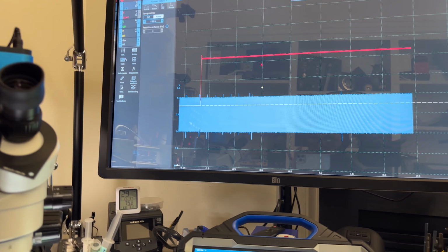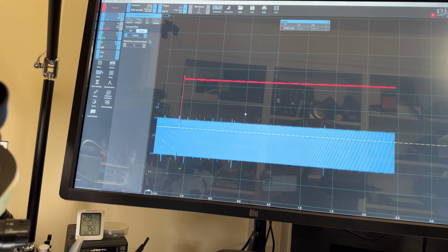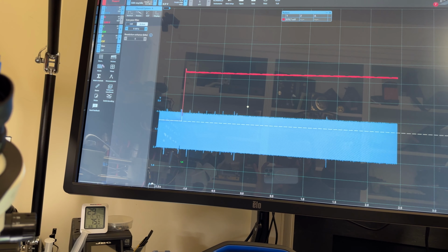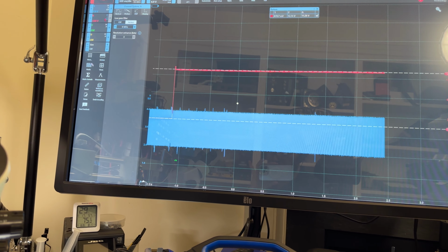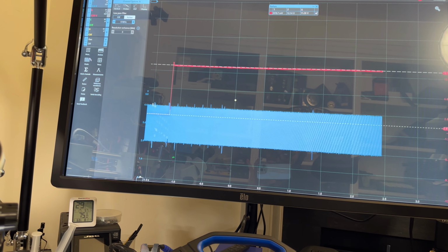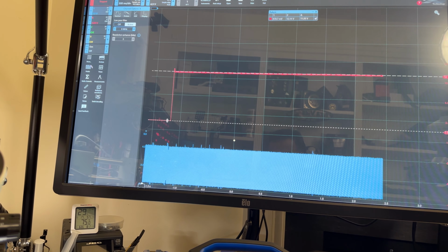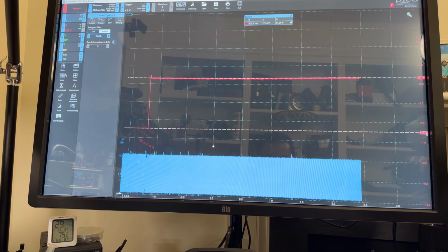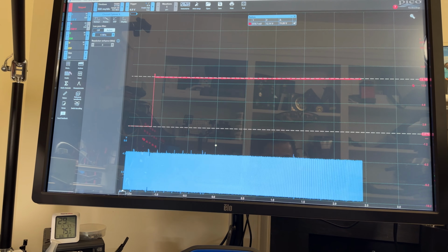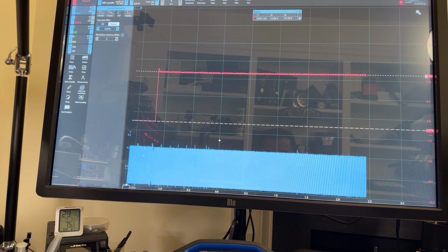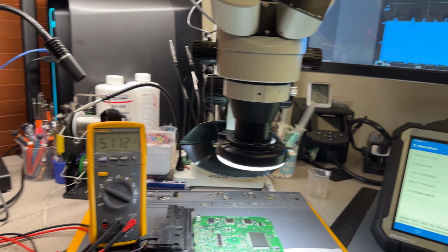And again, this is just analysis from the time base that I'm recording, but we can see completely the voltage going from battery voltage. I can even, well, let's just move this a little lower. And I'm glad that I have the auto cursor in here. So 0.8. If I go closer, I can guarantee you it's going to be better. But this is perfect. So this computer is working 100% now. We got complete communication. Everything is good.